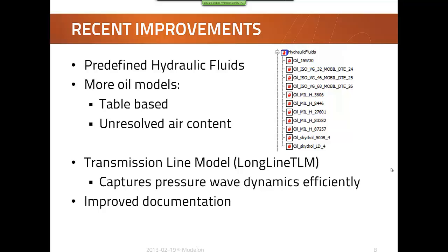We also have added more oil models, which can, for example, be table-based media. You can have unresolved air content in the oil. For example, there is a Nykänen and a Gibson model. And it's also possible now to include hydraulic oils or fluids defined by the Modelica fluids library. So you can, for example, use water content in the same hydraulic model if you want to flush the system or simulate something like that.